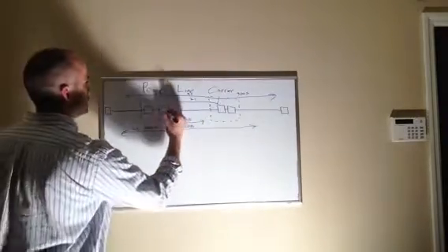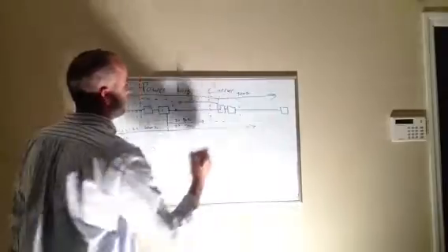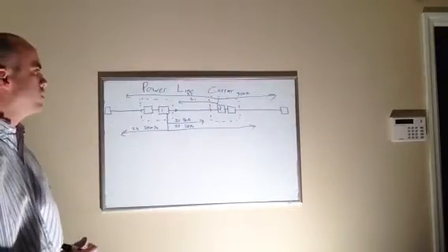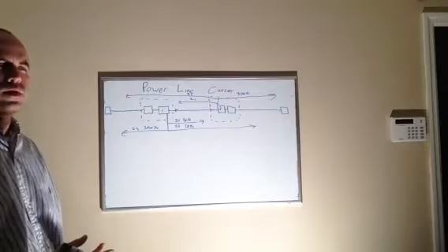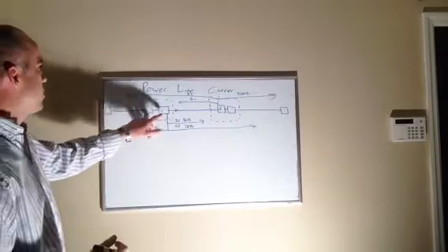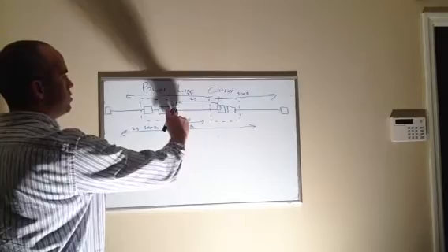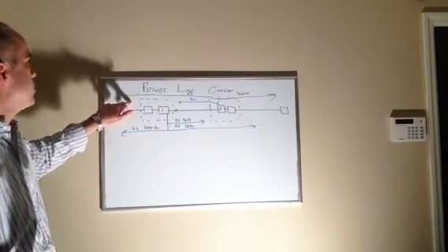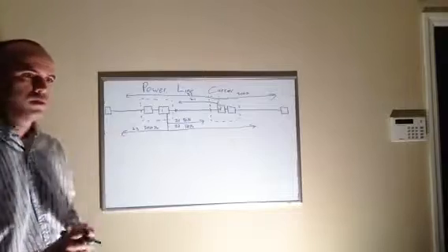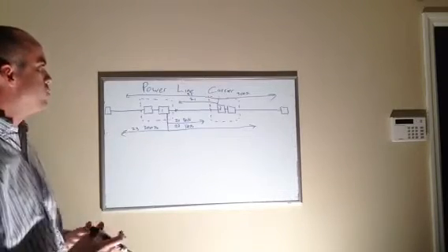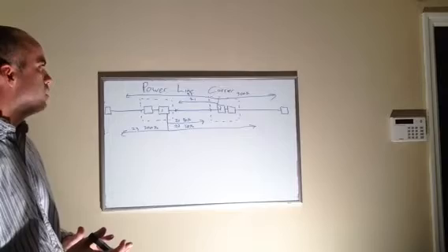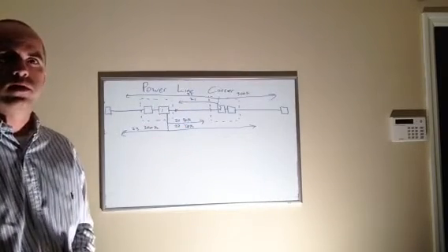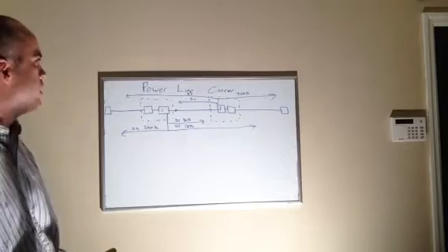This breaker we'll call breaker 1, we'll call this one breaker 2. Breaker 1 here, Zone 1 is going to see it. It's going to trip high speed. Zone 1, instantaneous trip. Okay, this breaker is just outside of this breaker's Zone 1. So these Zone 2 relays are going to see it. Now Zone 2 tends to be about 20 cycles as opposed to an instantaneous high speed trip. But we know the fault's in the primary line segment, so we don't want to wait 20 cycles to clear the fault. We want it to trip instantaneous.